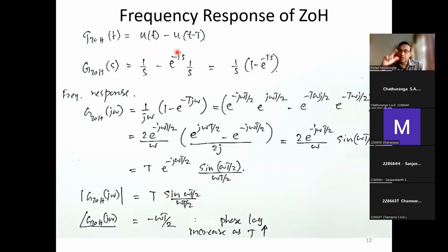Now, this is one thing. The other thing I want you to know is that when we analyze transfer functions in terms of their frequency response, how they handle frequencies, we substitute j omega in place of s. You know that, no? So in undergrad also we did that. S equals j omega, which means pure frequency response. You have the input sinusoidal waveform, which is not decaying or increasing either. It is the sustained pure single frequency oscillation.